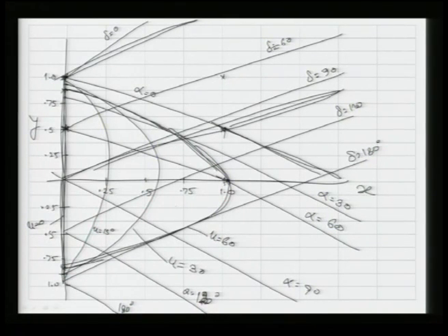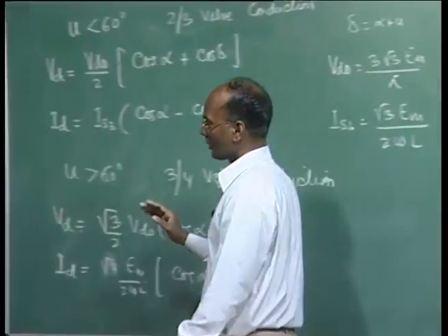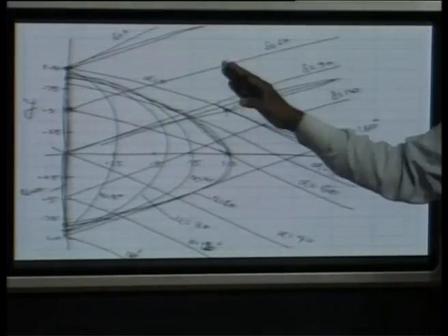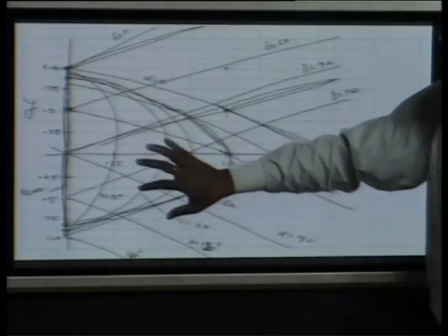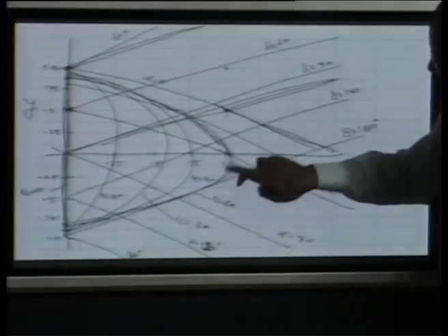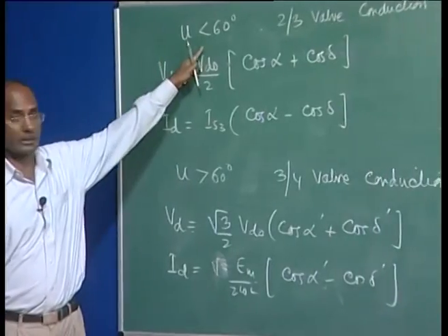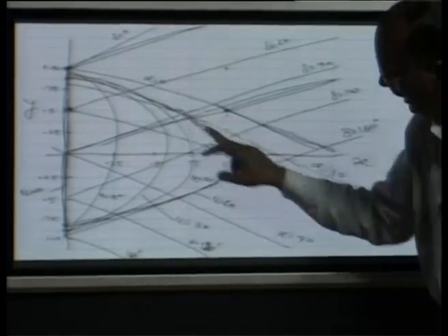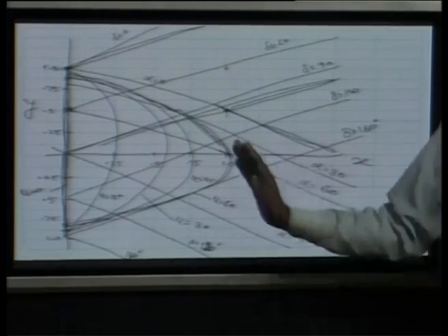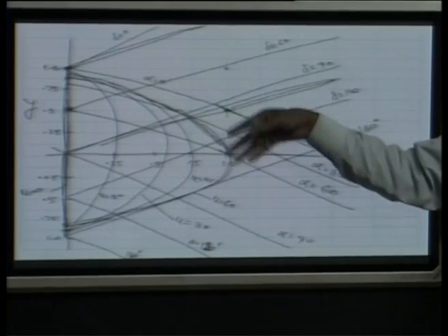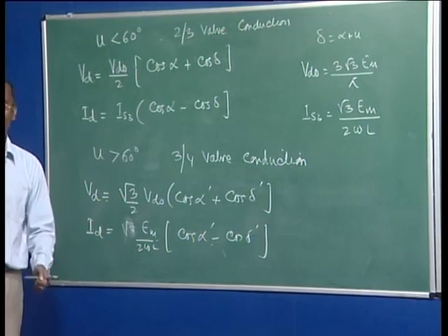If you are going to have u equal to 45 degree, it will be slightly less here, and we are going to have here that is u equal to 45 degree. So, this is the characteristic which we are getting. Now, you can see this is our boundary limit, because these characteristics, even though that is valid, will not go beyond, we have to stop here within this constraint, because the governing condition for your delta u etc. is in this zone only. We derived all these things based on this. So, your characteristic now lies only between this for u less than 60. For u more than 60, we will see we are landing somewhere else. Basically, we will be coming outside, but this alpha and delta will be changed, because here we will see the slope of characteristic is also going to change.